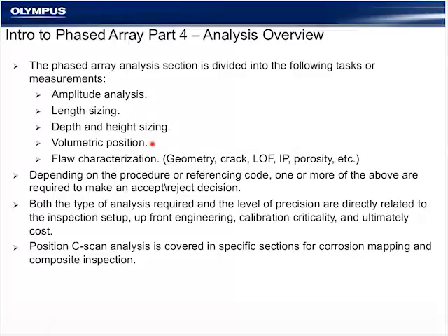The location or volumetric position is normally our number one indicator next to A-scan characterization and two-sided detection for telling us what type of flaw it is, meaning porosity, slag. In a typical V-weld, all of the different types of failure mechanisms, lack of penetration, inadequate penetration, and so forth. Again, volumetric position is our key indicator.